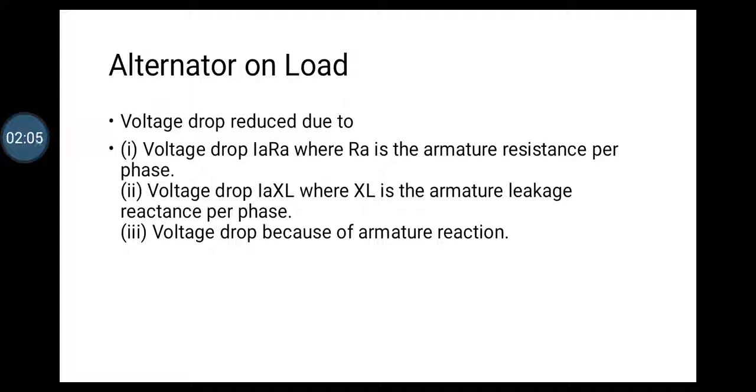Therefore, when the current is flowing, the Ia XL, that is the armature leakage reactance, voltage drop will occur. So this is also effective in reducing the terminal voltage.